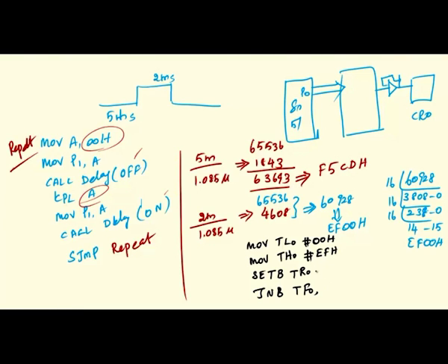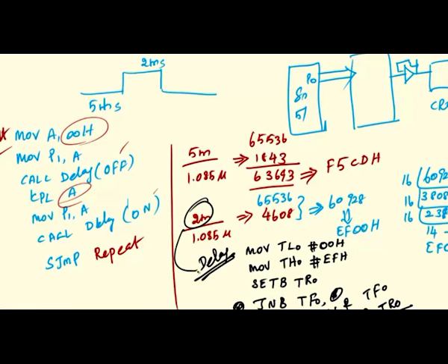So, once you are initializing the delay in the timer, we have to run the timer. So, we have started, then the process will continue till the timer overflow occurs. Once the timer overflow occurs, then you have to clear TF0 and clear TR0. That is, we are clearing the overflow flag and also we are stopping the timer. Okay. So, by this way we can initialize the delay. This delay for 2 milliseconds I have written, the same program we have to repeat for the 5 milliseconds.